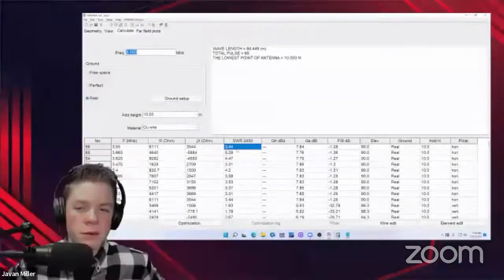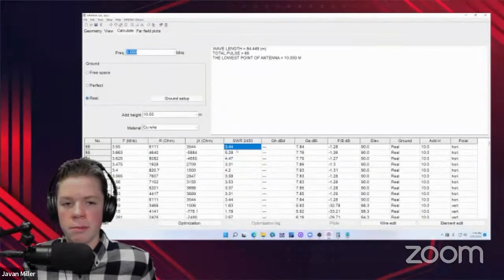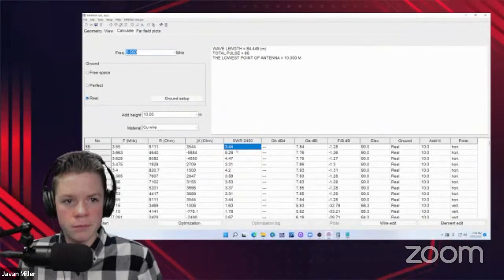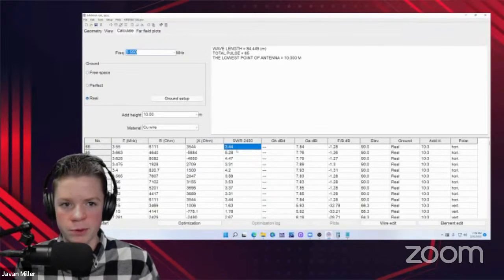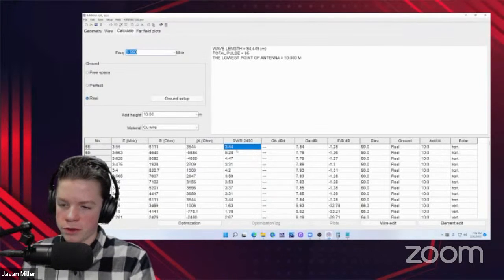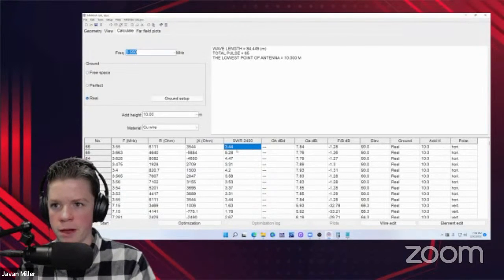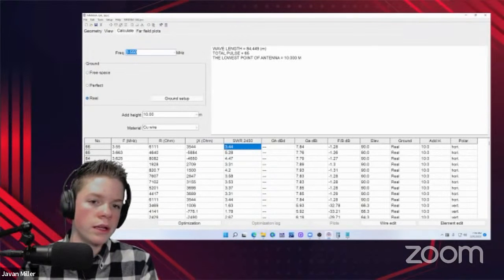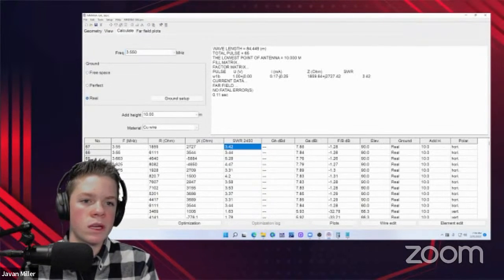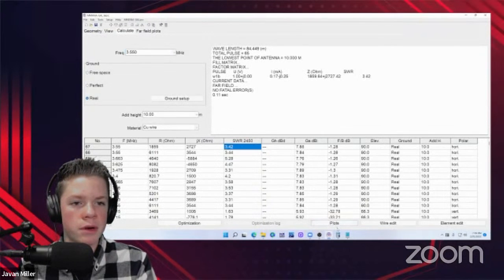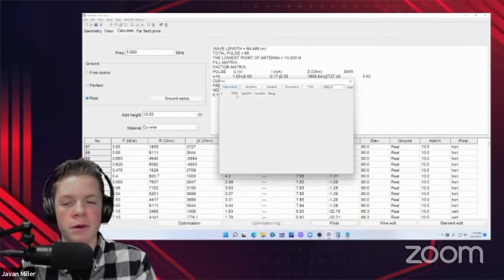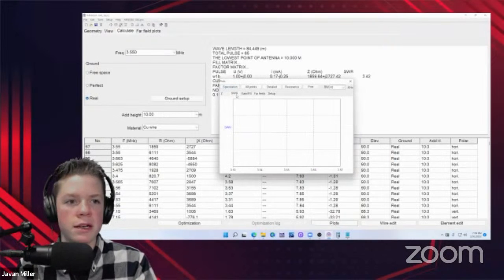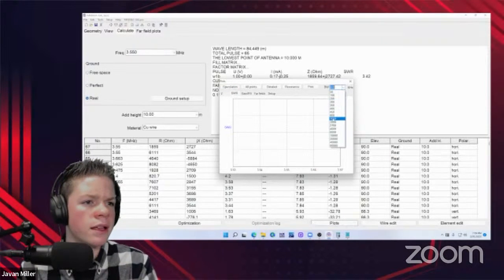Yep. But as we're seeing right here on 80 meters, the impedance is much higher, around 2450 ohms. So 64 to 1 would be better in this case, but we'll look at the higher bands and see what it looks like. So let's see here. That looks like it brought the resonance higher on 80 meters. So let me run another scan.